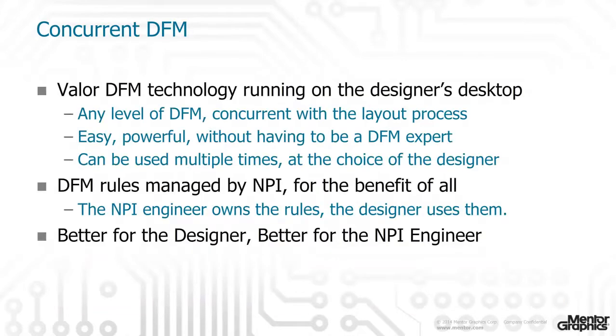The DFM rules are managed on the design network by the NPI specialist for the benefit of all the PCB layout engineers. Integrating DFM into the design process, but without calling for the layout people to suddenly become experts in manufacturing process rules. It all connects to the emerging trend in electronics design to concentrate more functionality on the desktop of the engineer designer. In the end, it is much better to find and fix DFM problems at source rather than wait for the NPI team to find them later at greater cost in time and money.